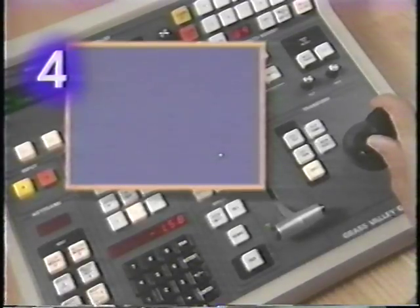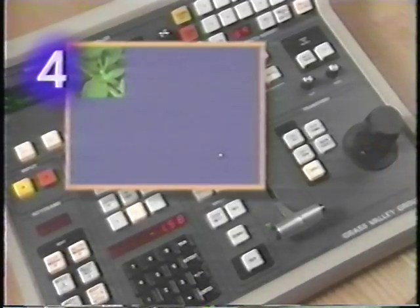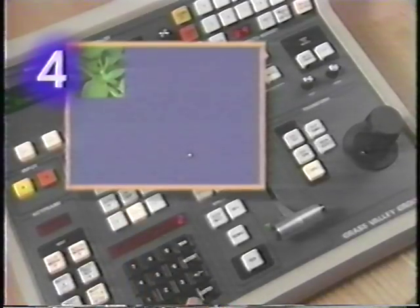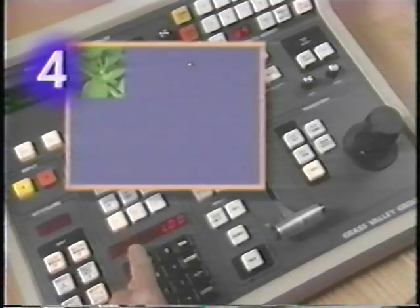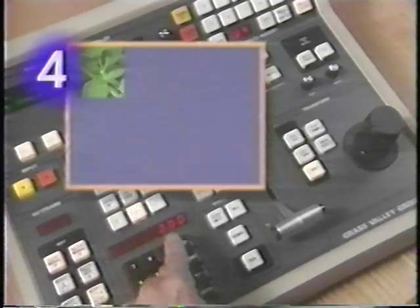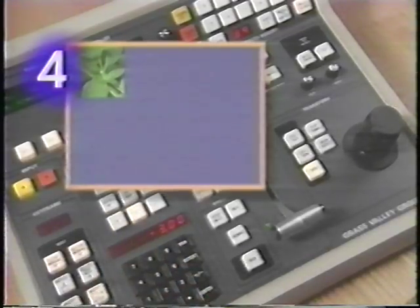You can also use direct entry to position your center of orbit. Select X or Y, enter a specific value on the keypad, and press Enter. Note that X values greater than plus or minus 4 and Y values greater than plus or minus 3 will move the center of orbit off-screen.